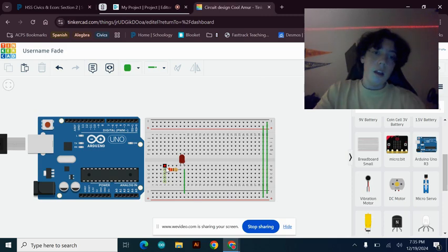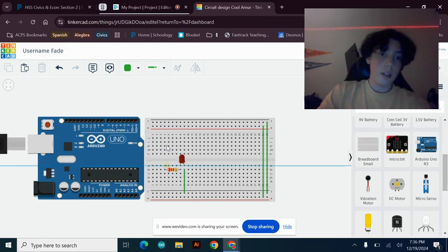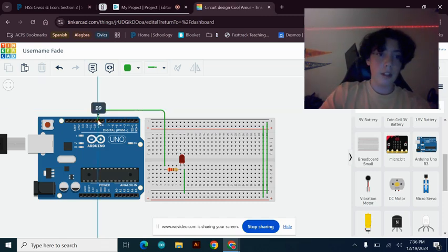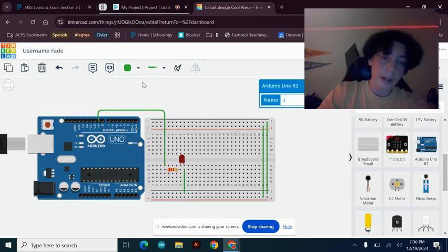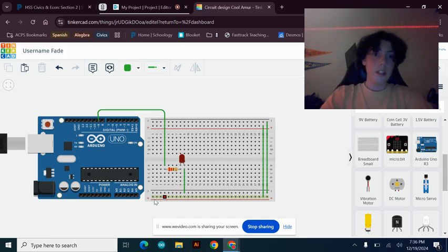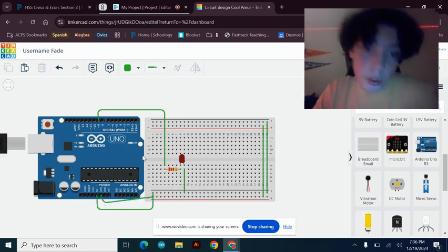Now, you're going to need to click E4, or the thing above terminal 1. Bring it up and connect it to D9, or the squiggly line and then the 9, so that it's connected to the Arduino. Then take the negative and drag that into the 5V so that it looks like this. Then take the positive that's right under it and add it into the GND, one to the right of 5 volt. So they should be right next to each other.